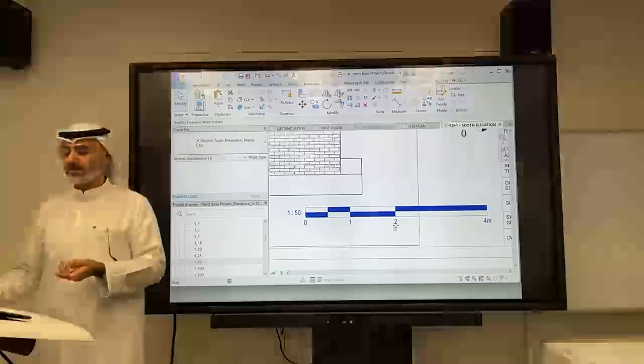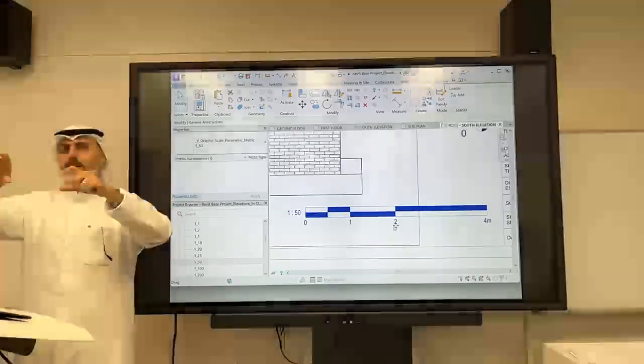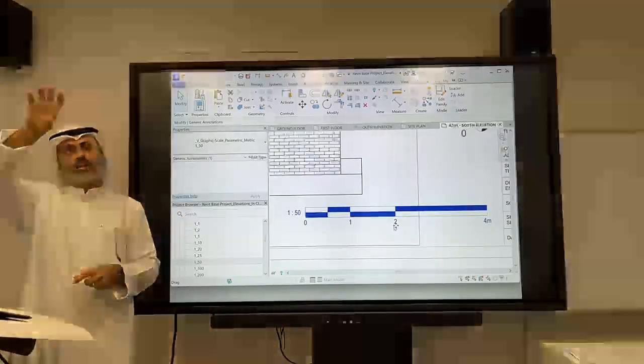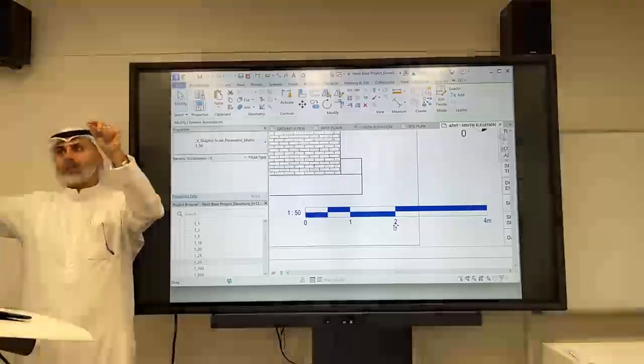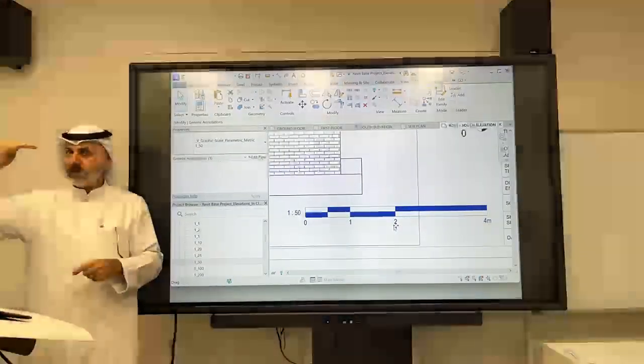Let's show you floor plans. Floor plans should all be in the same location. Use a reference point and locate your ground first, second from the same reference point. When you flip through the PDF, they are all in the same place.